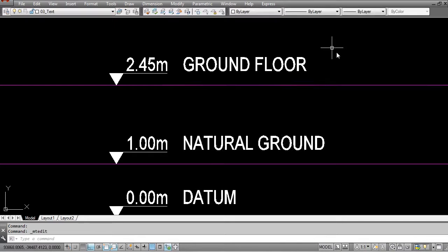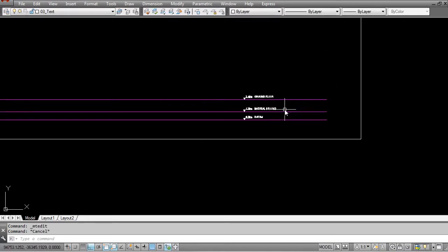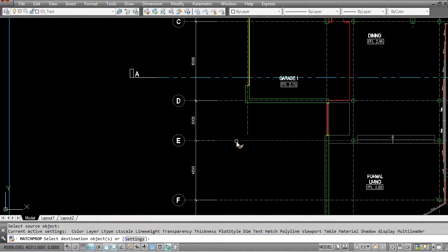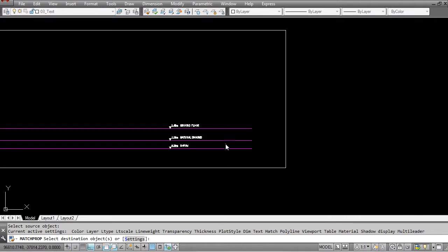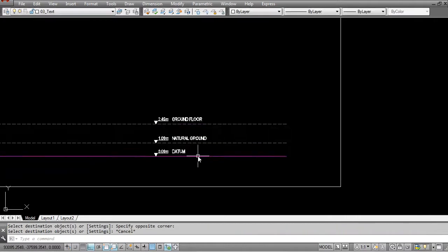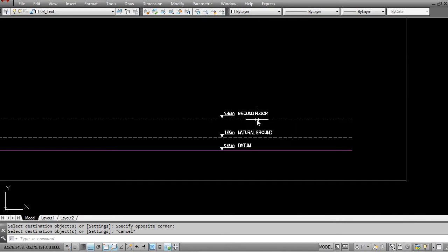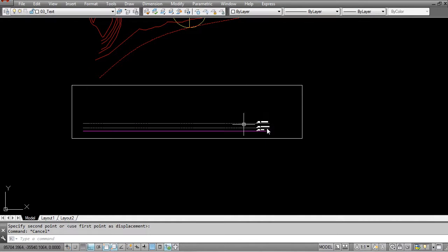natural ground. So for these lines, what we want to do is get a dashed line as well, so we can get an idea that the ground is being cut through, which is this thick line, and then we're going to have these dashed lines which are going to be showing our heights. This can be brought in, and that is already the foundation of our section.